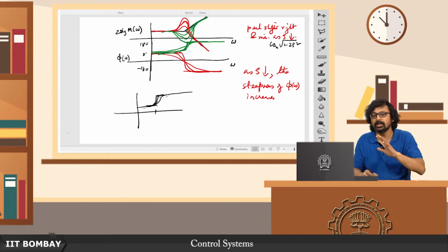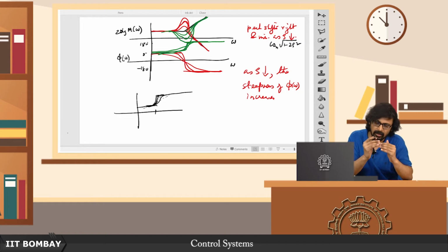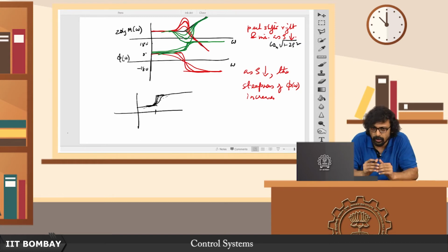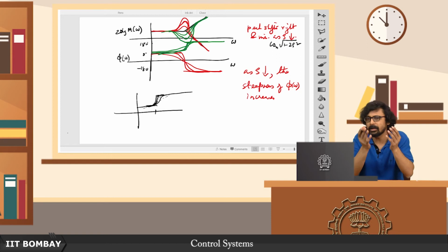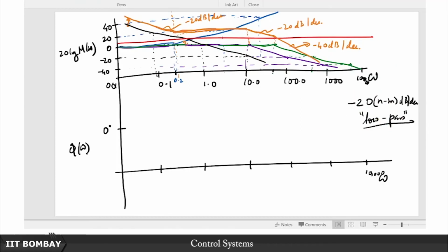So I just want to draw this Bode plot as quickly as possible, and then gauge what the qualitative Bode plot looks like. If I am very particular about the exact numerical values at several points, I better use MATLAB or something like that. There is a command in MATLAB, bode. So you can use that if you want very high accuracy. But if you just want a quick sketch, I am not going to take this trouble. So already in the phase plot I am going to use that.